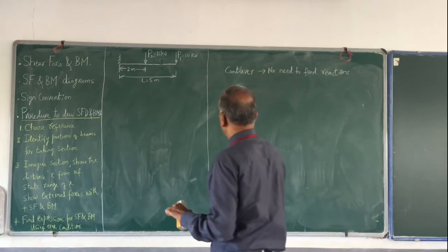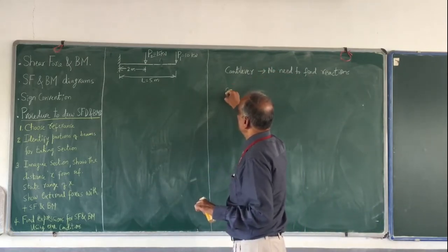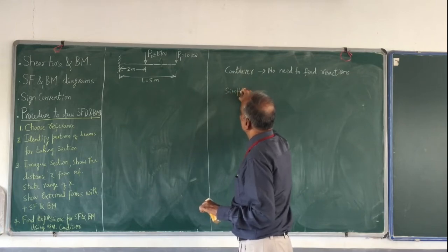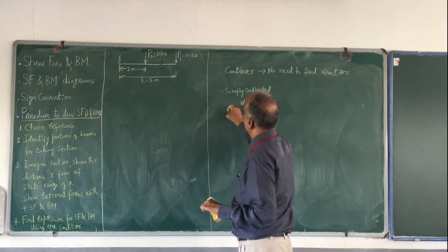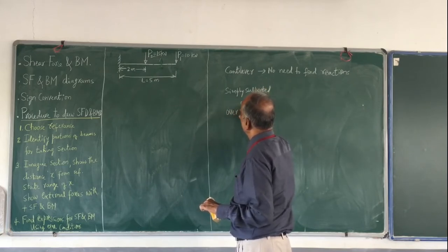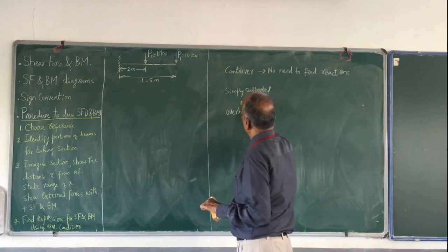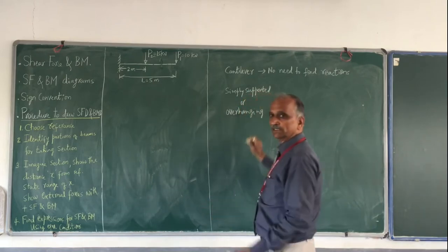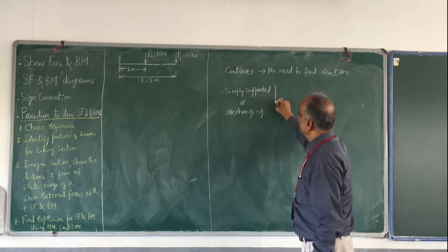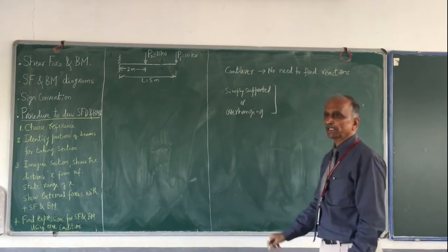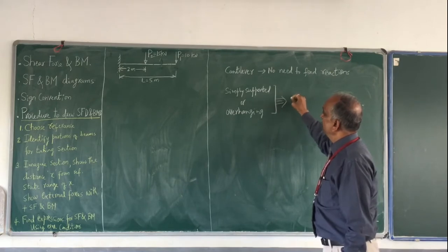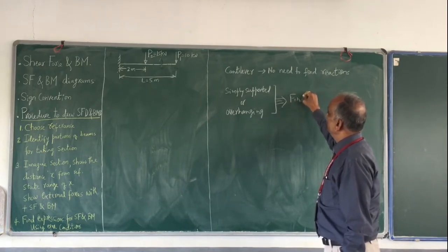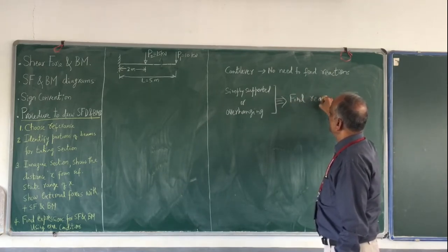But if we are discussing a simply supported or overhanging beam, if we are trying to draw the bending moment and shear force diagram for this kind of beam, your first step is to find reactions.